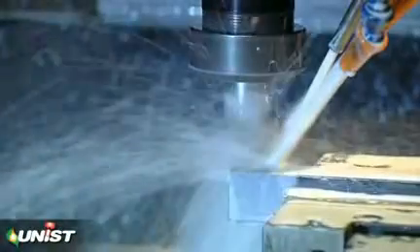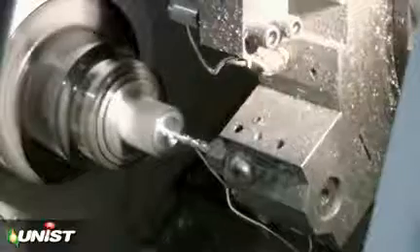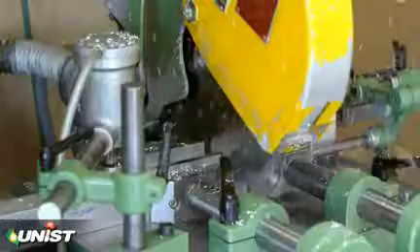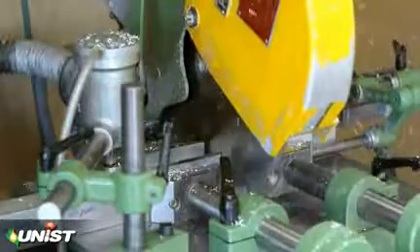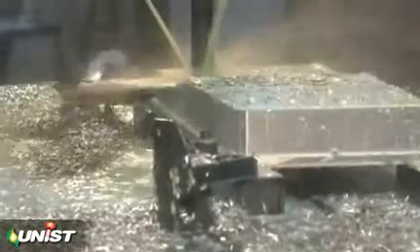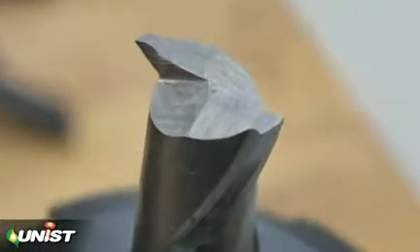Every type of machining operation faces the same challenge: how to handle the friction and heat created when cutting tool meets metal. Metal cutting begins when the cutting tool penetrates the workpiece and begins to form a chip. The friction created between the tool and the chip creates extreme temperatures in both the tool and the workpiece. This increase in temperature actually changes the molecular structure of the cutting tool, causing it to wear.